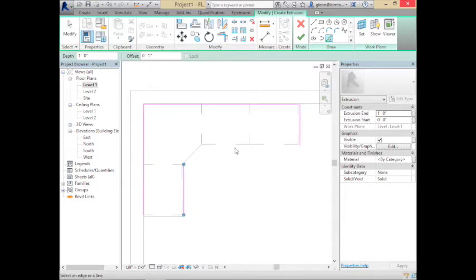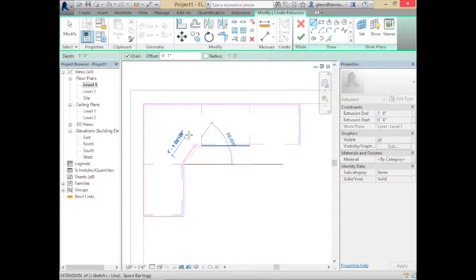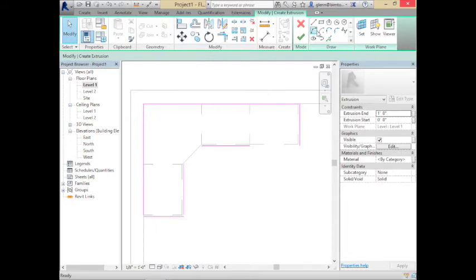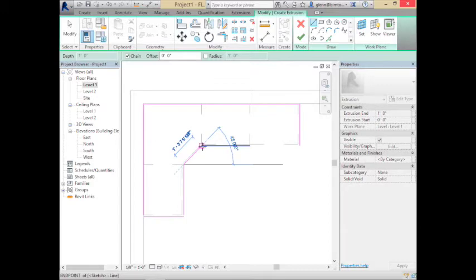And I'm actually just going to offset all around the front because the truth is when I do my cabinets, it looks like, oh, is that one going to offset for me? That one may not. I want it to, but it doesn't look like it's going to. Odd. I'll draw it then. Oops. Actually, watch out with this. If you have an offset set and then you choose draw, it doesn't draw the line where you want it to. Okay, so, famous ways I get myself in trouble. That's one. Okay. Now I'll just draw from the endpoint there to the endpoint there.